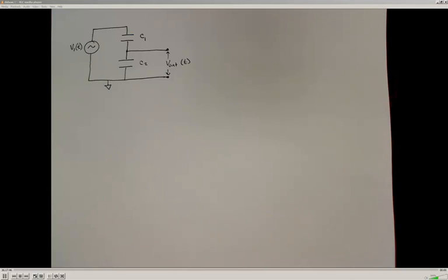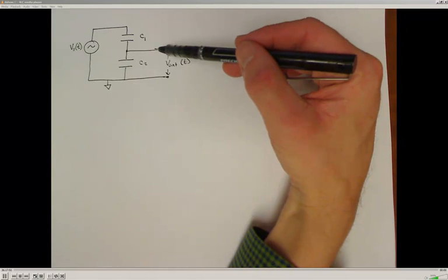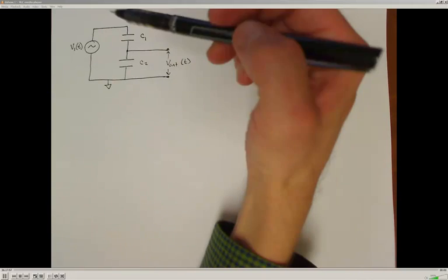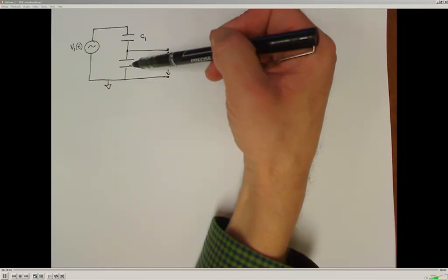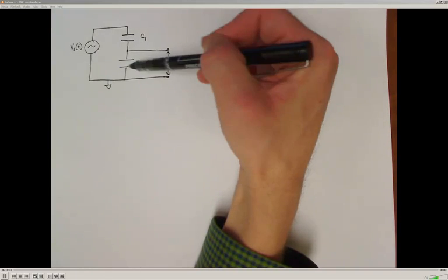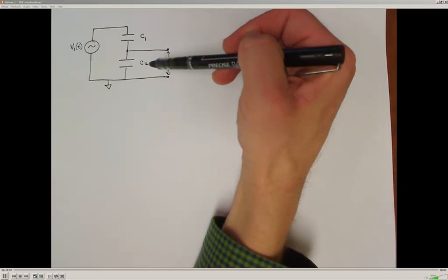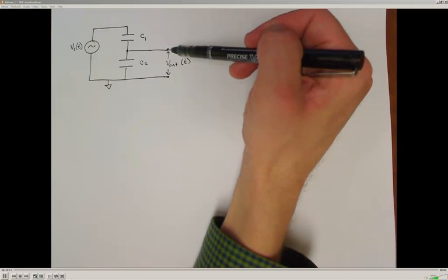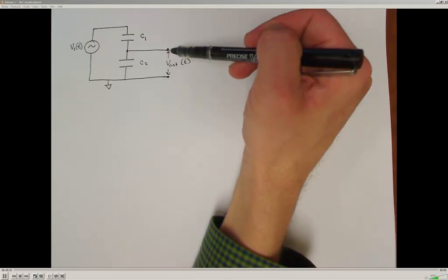In this example here, we're going to look at how capacitive elements are used to measure changes in capacitance. And this circuit is analogous to a voltage divider circuit with a resistive circuit. So this circuit that we see right here is also a voltage divider circuit, but it's a capacitive voltage divider circuit. And this is a common circuit in a lot of modern touchscreen device applications.